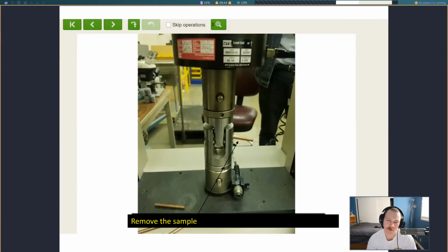You're going to export your data, and this is what it's going to look like in the end. It's going to shear in two different spots because it's a double shear lab. So we're shearing right here, and we're shearing over here. This part got a little stuck here. This one fell down. Then you're going to get the material that's in the center here, and you're going to take that out, and you're going to record that length.